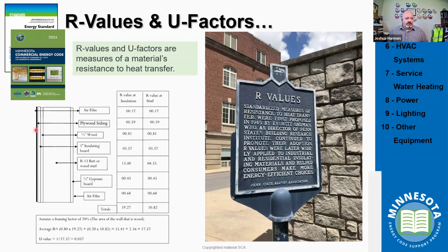So we're looking at sheathing, we're looking at exterior wall coverings, we're looking at potential continuous insulation, cavity insulation, drywall. All of those elements have a thermal resistance capacity. It may be very low in certain instances, but we're going to calculate all of those, weight them across the wall assembly, do some math, which we're not going to get into, and then that gives us our U value, right?